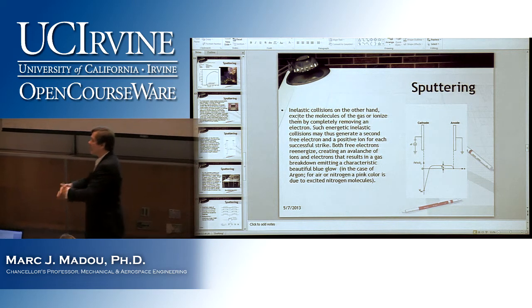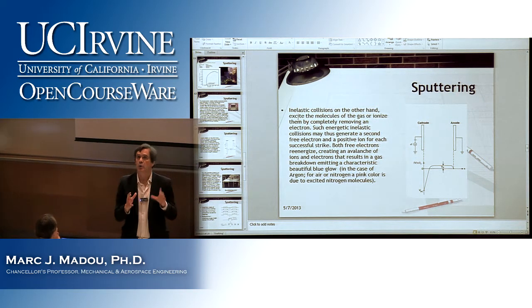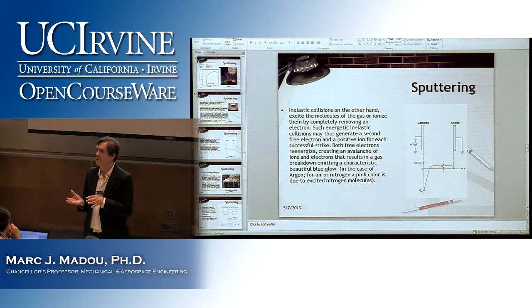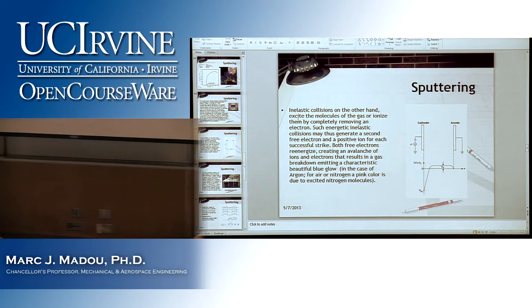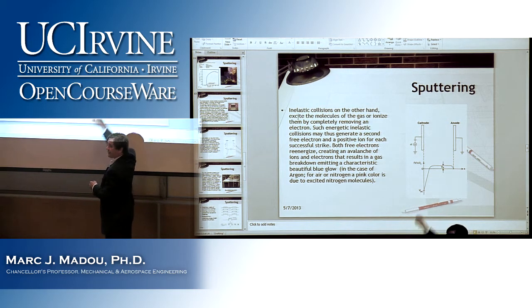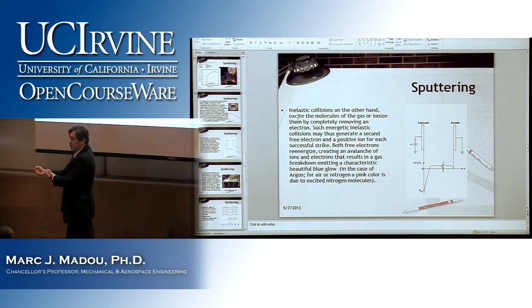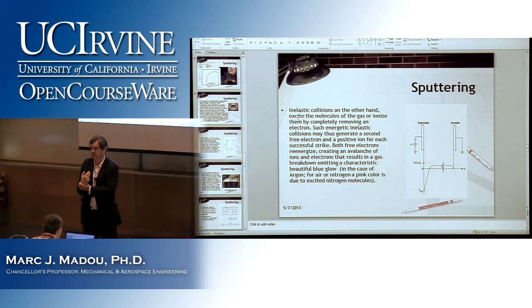So now, adding to that, if you want to do etching, where will you put your workpiece, on the anode or the cathode? And why? The negative, and I don't know which one that is. You want to put it on the cathode. And the reason is, that's where the argon, if you see this big drop here, the argon plus ion gets all of this extra punch, right? Because it runs into that field with high velocity and knocks off atoms from the workpiece.